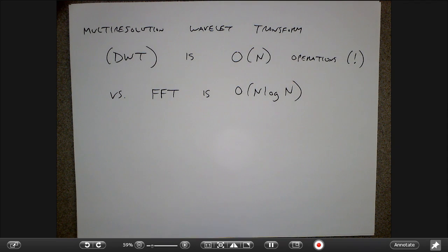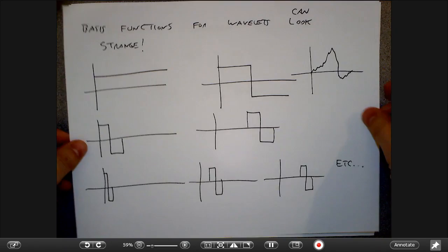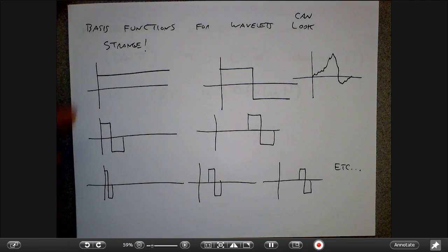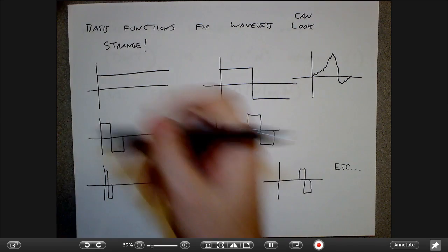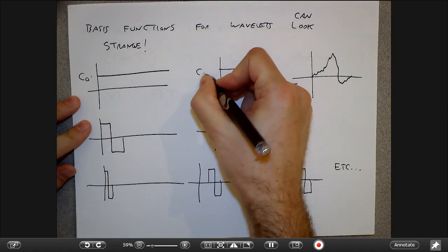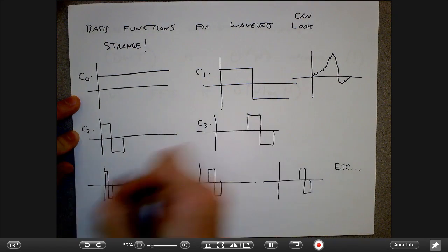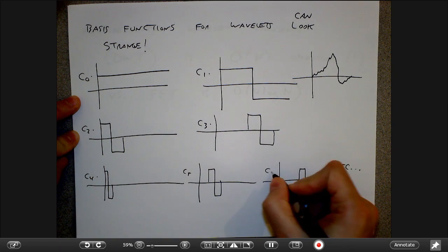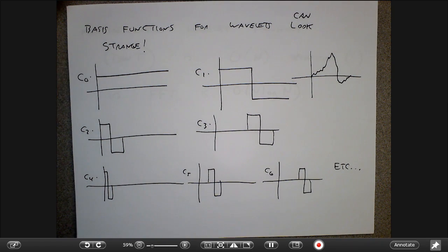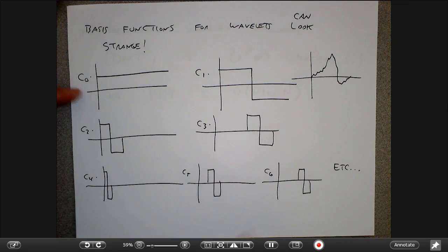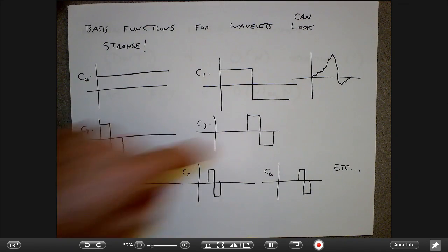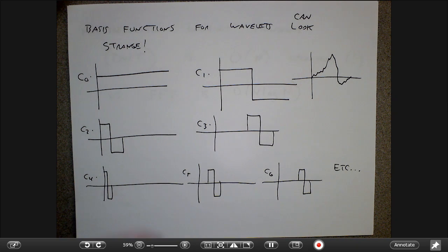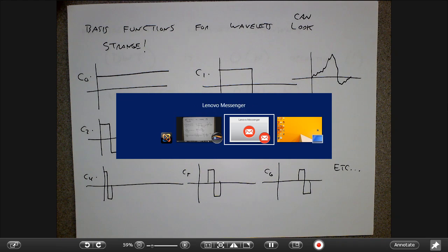So to go into the 1D case for a second, what I'm doing with a 1D wavelet transform is I'm fundamentally representing my original signal as some coefficient times this plus some coefficient times this. So basically, this is the decomposition of 1D. You can think about it as separating my original signal into a sum of basis functions in exactly the same way that we drew sines and cosines for the Fourier transform, right? For an image transform, you're basically doing a wavelet decomposition both in the row direction and the column direction. And actually, it's probably easiest just to show you. I'm sure we can find a picture of it.